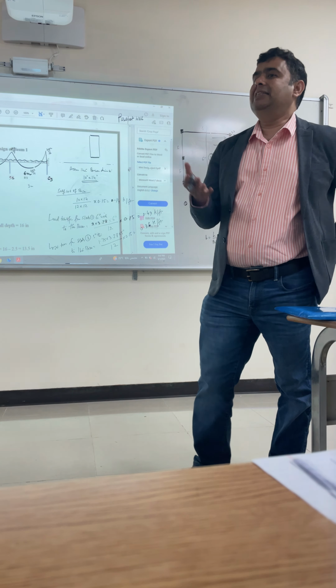Got it? What is live load? Live load transfer. We consider 40 pound per square feet. Live load of 40 pound per square foot is transferred from slab 1 and 2 to the beam. How will you calculate? You substitute the 40 by default. The live load is 40 by default.